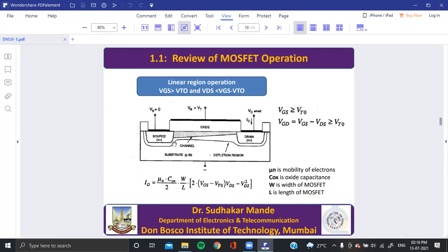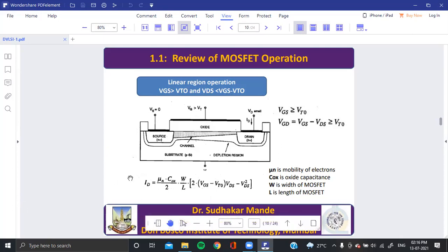So why MOSFET works in linear region? Because if you see here, inversion layer is there at source end. I'm pointing here. At the same time, inversion layer is here at drain end also. Can you see this? Both the points? The channel is there, but like linearly increasing.